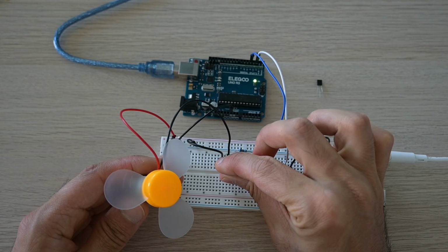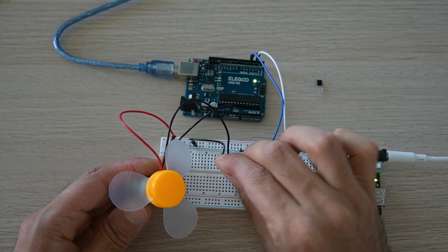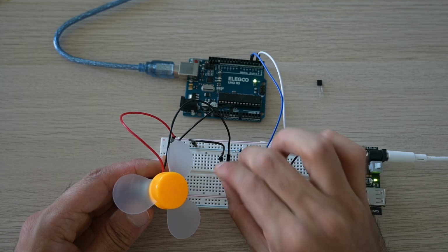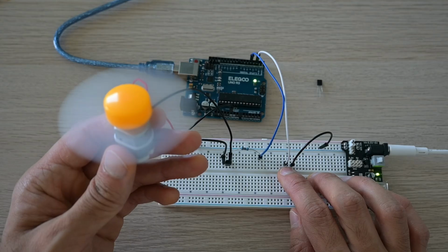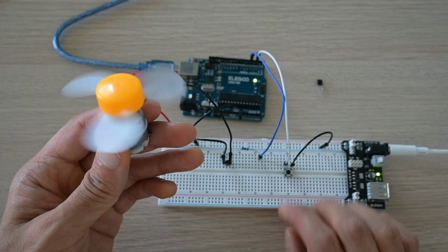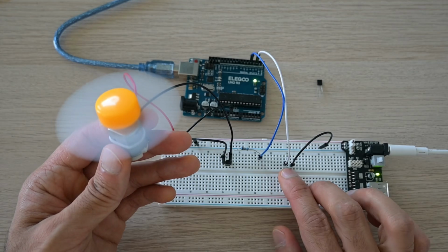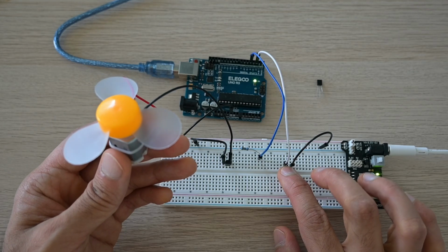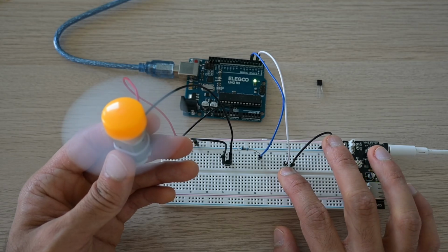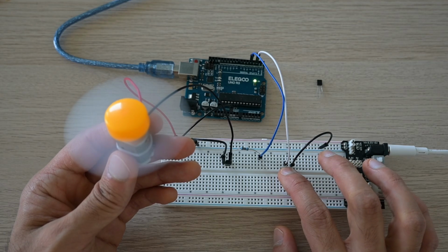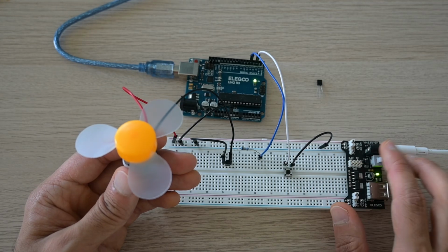The kit comes included with two models of NPN bipolar junction transistors, the PN2222 and S8050. Both are often used interchangeably, as seen here in this video, but the PN2222 has a higher voltage rating for collector to emitter voltage, so 60 volts versus 25 volts, which in this case is not very relevant since we're not surpassing the 5-volt barrier. In these, the base is the valve, and the collector and emitter function as the pipes.